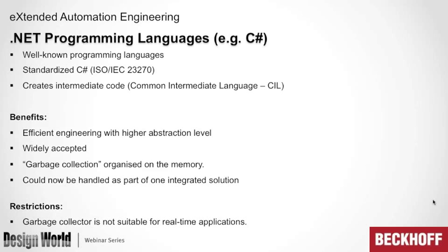It's often asked, can I do control with C#? And the answer is no. Fortunately, because C# has an automatic garbage collector, and it's the same for Visual Basic too. We have to consider those what we call user mode, the non-deterministic area. At the same time, we have our deterministic, our highly cyclic environment, and our user mode stuff. We're all in one programming environment.